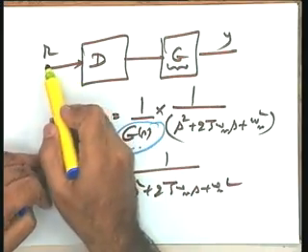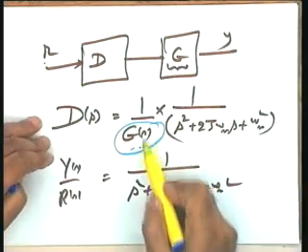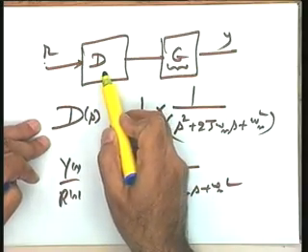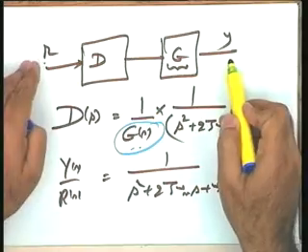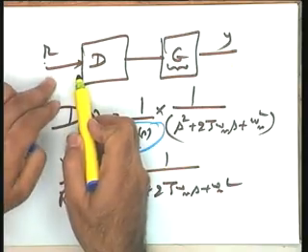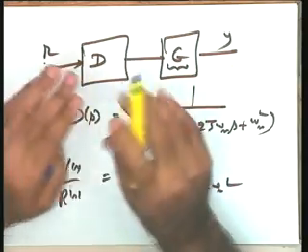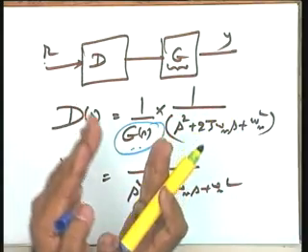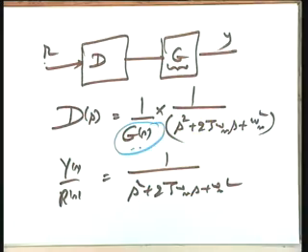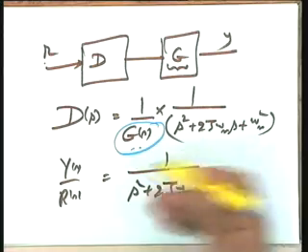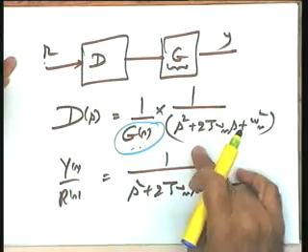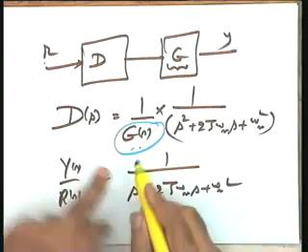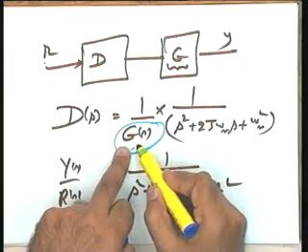And therefore there will be an error between Y and R because of this imperfect cancellation. And since the controller has no knowledge about the error, there is no feedback action going on here. So the controller is not an intelligent controller, it has no information about the errors. Those errors will keep on building up and your system may become unstable. And therefore such a controller, in which an open loop pole dynamics cancelling attribute is used, is never utilized.